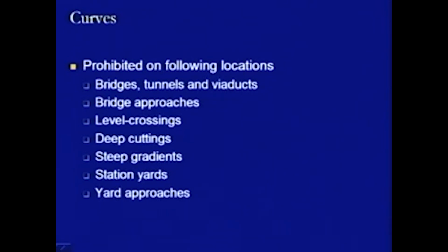In the case of deep cuttings also, the curve should not be provided, because it increases the length, and when it increases the length, the cost of cutting is much more than the cost of embankment. It has an economic or cost consideration.